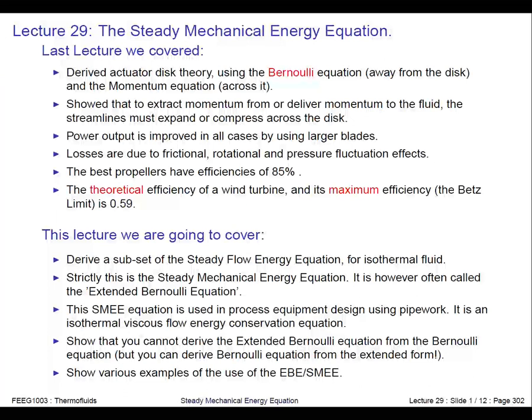And if you want to put a pump on a pipe network, this equation will tell you what kind of pump you need, how big it should be, what the losses are going to be, and how you should design your pipe such that you can minimize your pressure drop and choose the smallest pump possible.